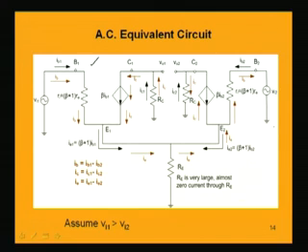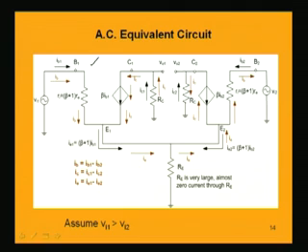Now, consider the resistance capital R capital E, which is connected to E1 and E2. The current which will be flowing through this resistance is made 0 by making RE very high. So, in this circuit you assume that the resistance RE is very large, and that is why the current through this resistance RE is almost 0. So, that assumption is made, or we have to basically make this circuit like this only, then we can proceed further easily. By making this RE very high, we are making the current through this resistance almost 0.